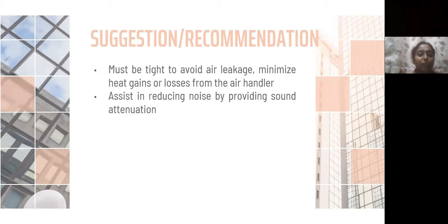Okay, for the suggestion part, the air handling unit must be tight to avoid leakage and minimize heat gains and losses from the air handler. It also needs to assist in reducing noise by providing sound attenuation.